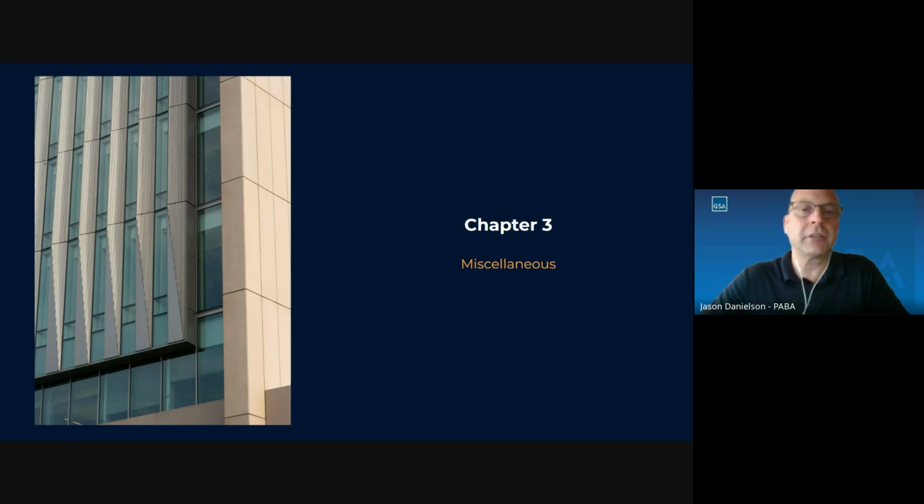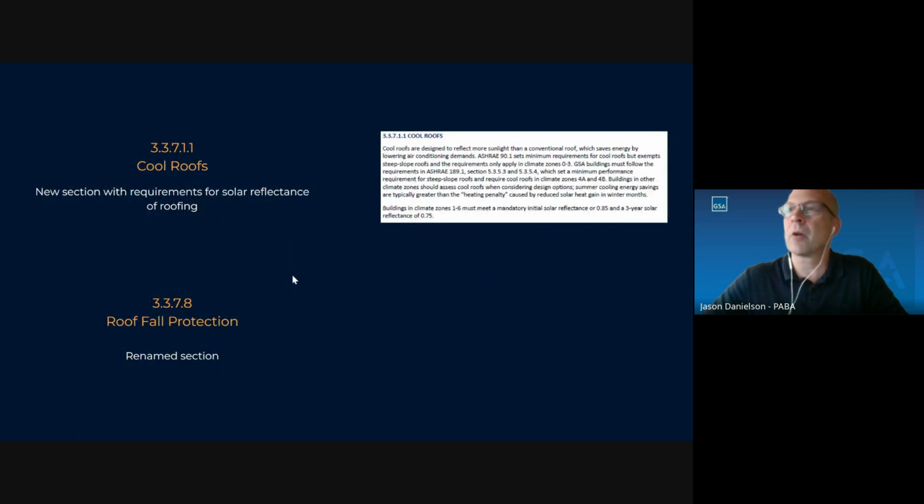All right, let me jump to the last one, chapter 3, miscellaneous, real quick. Cool roofs. This was a new section altogether with requirements for solar reflectance of the roofing. The initial solar reflectance is 0.85 and the 3-year solar reflectance is 0.75, and those are for climate zones 1 through 6.